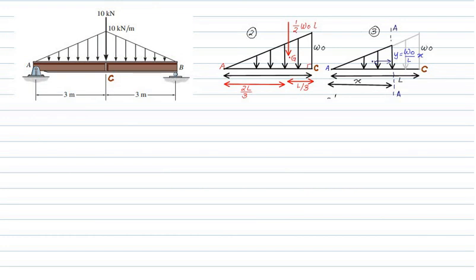So we have a simply supported beam and we have two triangular loads with a maximum load of 10 kilonewton. Is it also a point load here? 10 kilonewton is the total load. Is it correct? Okay, what will its total value come to? 10 into 3, 1 by 2, that is 30, 15 plus 15. What is the load of this triangle?